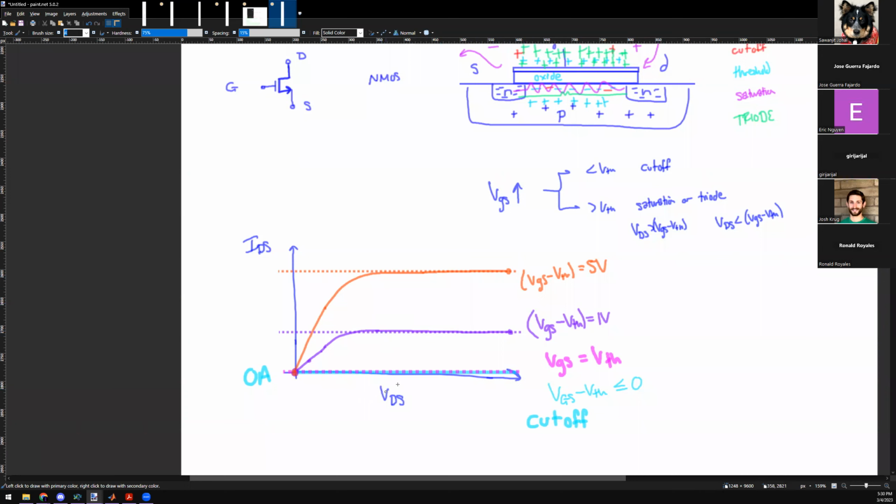All right. So does the VDS IDS curve make sense? That linear region here would be the triode region. It's basically where VDS and VGS decide. So for me to find this limit, what do we need to find? I need a plot where VDS is equal to VGS minus VTH, right? Yes.